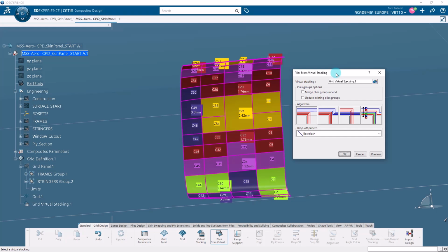However, it creates more complex ply boundaries that might make the part more complex and expensive to manufacture. Finally, the weight-saving method is used to create ply boundaries that cover the minimum necessary area, but may result in ply definitions that, due to their many ramp crossings, have more buildup on the ramps than would be produced by the other two algorithms. In our case, select the minimum crossing algorithm.